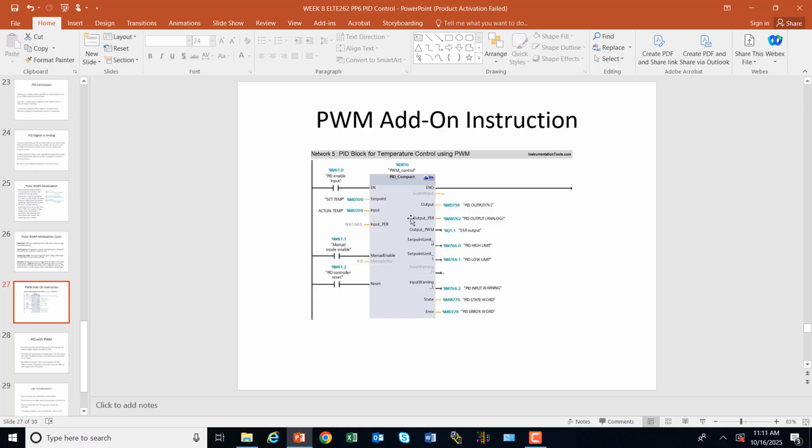And it's going to say, hey, if it's more than 20 degrees difference, it's too cold, let's heat this thing up fast. And maybe when it gets within 10 degrees, you slow down. And then at 5 degrees, you slow down even more. Then at 1 degree, you slow down even more.